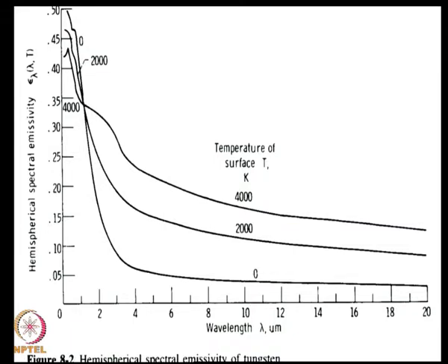So, we get very good information from this work, which is that the assumption of a gray surface in a given situation is sustainable if the temperature difference between the different surfaces is not very large. But if the temperature difference is very large, then a gray surface approximation can lead to errors of the order of 30 or 40%.